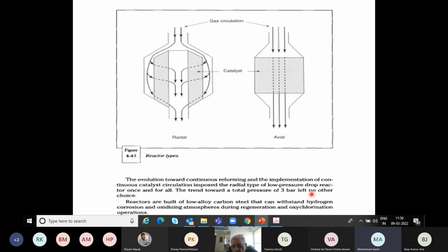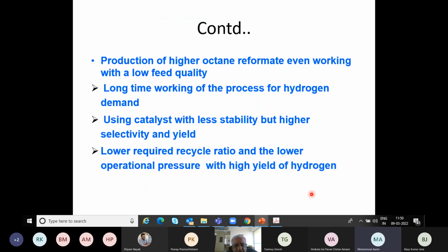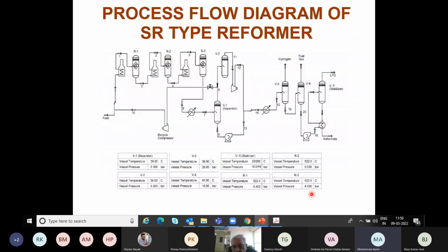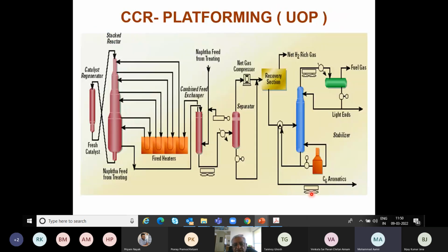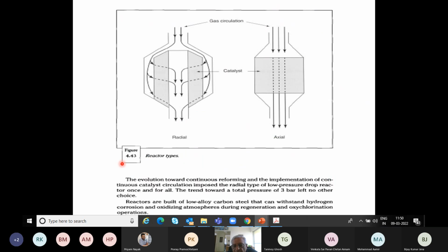And one more thing which I wanted to tell you. From the diagrams that you must have seen, you must have got a feeling that we fill up the entire reactor with catalyst. That is not so. Remember, we cannot afford to have high pressure drop through these reactors.